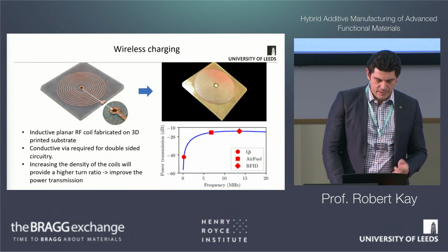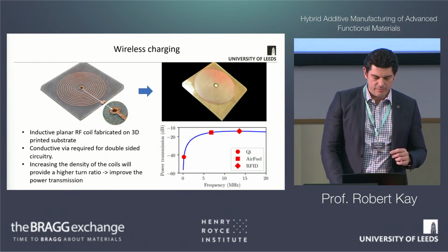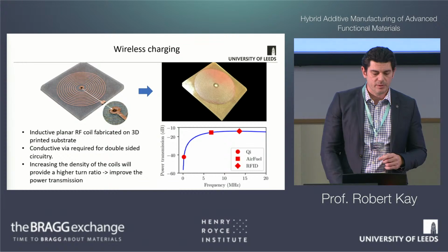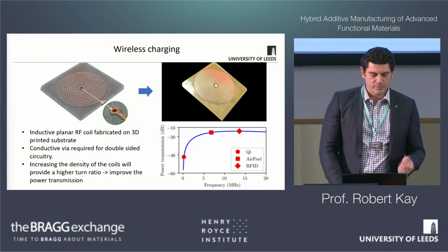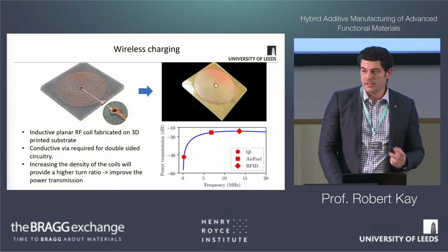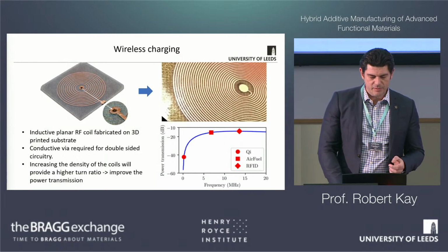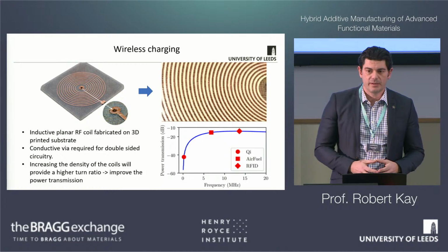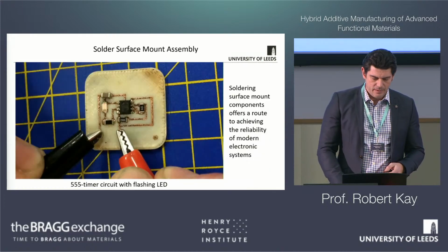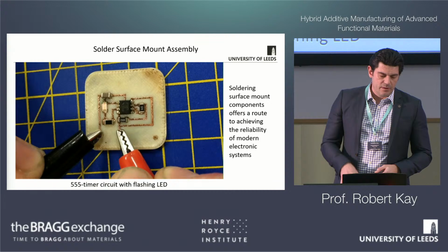So we were very pleased to see that we were able to get the AirFuel and the RFID standard, but with the one that we made, we had too much return loss to hit the Qi standard. However, more recently, we fabricated one that has a much higher turn ratio, which should overcome that issue, basically.